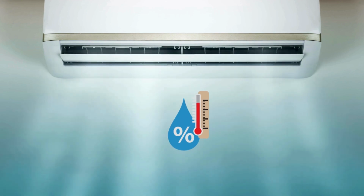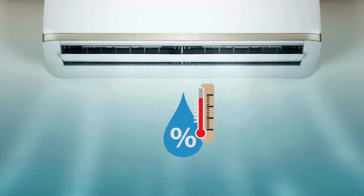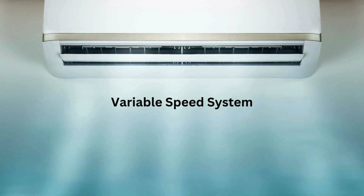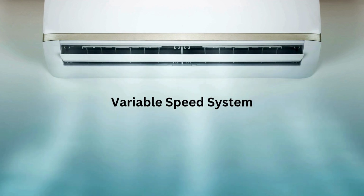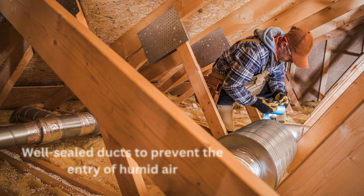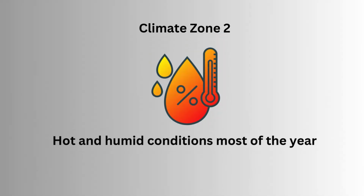Due to the high humidity, systems need to control moisture as well as temperature. One of the best ways to do this is with a variable speed system. Proper dehumidification is critical to avoid mold growth. Homes also require well-sealed ducts to prevent the entry of humid air, which could degrade performance or cause moisture issues inside walls and attics.